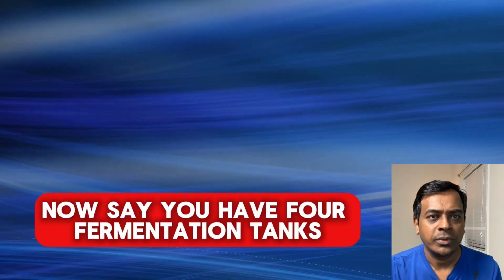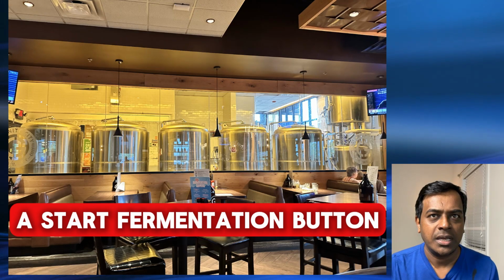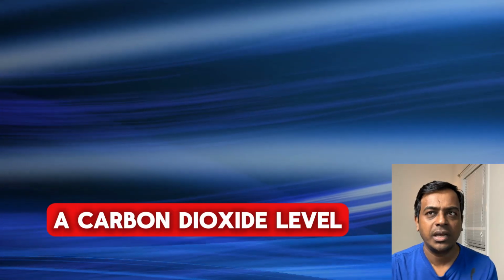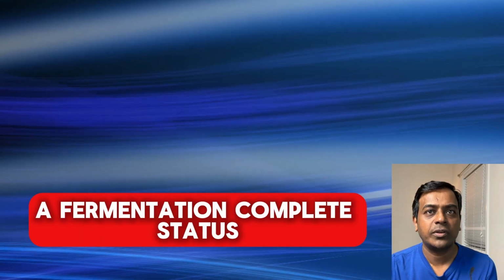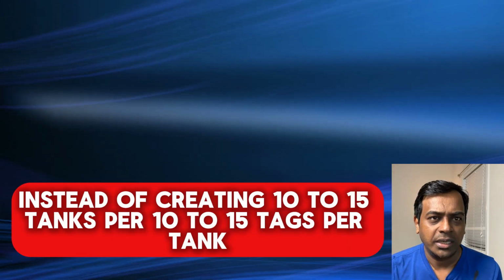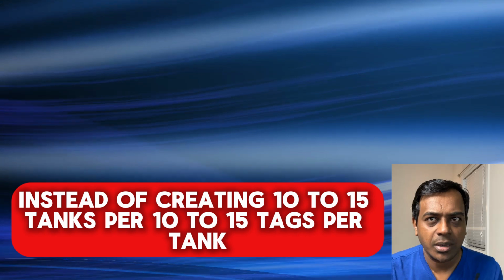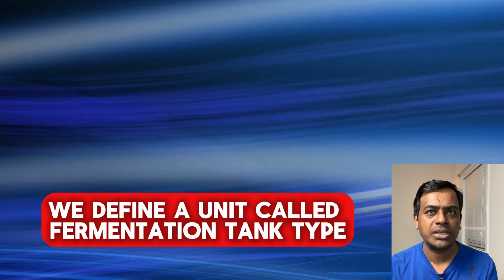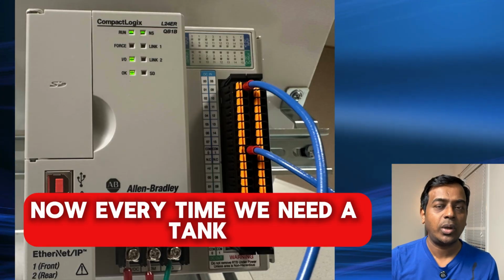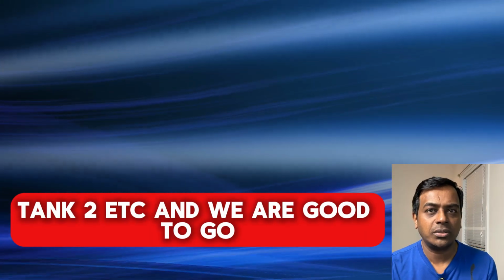Now say you have 4 fermentation tanks. Each one needs the same kind of logic: a start fermentation button, an emergency vent, a temperature sensor, a carbon dioxide level, a fermentation complete status, and some internal control variables like timers or PID settings. Instead of creating 10 to 15 tags per tank, we define a UDT called fermentation tag type. In this, we will include all the relevant bools and reals and integers. Now, every time we need a tank, we just create a new tag and call it tank 1, tank 2, etc. and we are good to go.